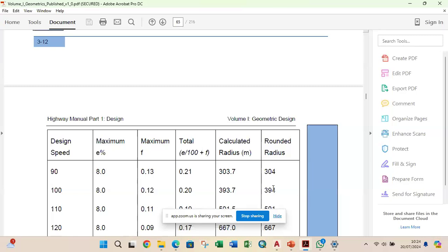So what that means is that I will be bringing my signage before and after the curve. I will bring what they call speed bumps before and after the curve, so that the driver is driving on that road, since my design speed is 100 kilometers per hour, and at that particular curve I'm below the specified radius, which is 394 for 8% super elevation. So I will introduce a design speed limit before and after the curve, like 100 meters before and 100 meters after the curve, and put the signage and the speed that the driver will use in navigating around the curve.